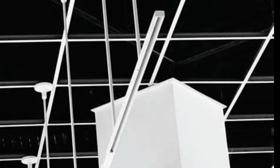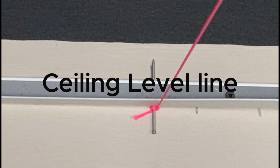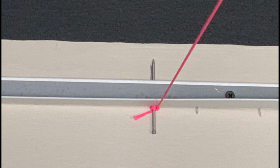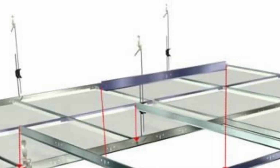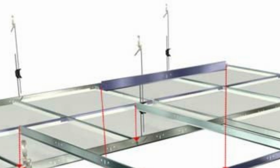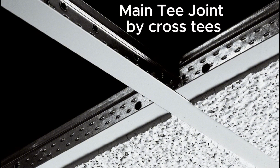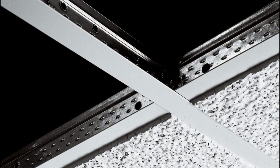If by chance a main tee should run in line with a building column, adjustments will have to be made by cutting the tees accurately to go around the column. An L-shaped metal strip, usually 12 feet long, is screwed into the wall at the final ceiling height. It runs along all 4 walls of the room, forming the support edge where the ceiling grid system ends. The ceiling usually stops at about 1 foot from the L shape, where ceiling tiles are cut to fit into the space. The L shape also supports the main tees. Check the level of all tiles using a laser or bubble level.